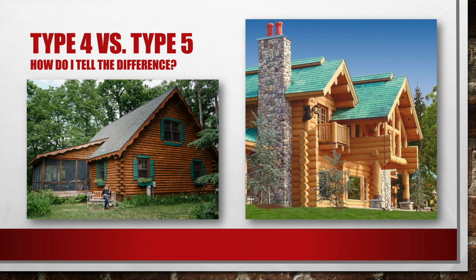Because if you remember, type 4 buildings have to have a minimum of a 2-hour fire resistance rating. These smaller logs probably don't have the minimum 2-hour fire resistance rating, which a much larger log with more surface area would give you.